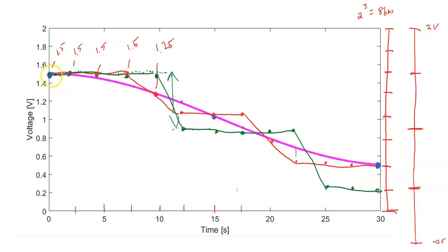What does that curve end up looking like? Let's see if I can draw it as a straight line. When we connect those points, we can see that the only curve you can assume through those 3 points is that straight line. And so if you were to try and interpolate what the actual voltage is at any time in between your sampling points, you'd be introducing this error that's not due to the size of your bins, but it's due to the fact that you're only sampling every 5 seconds.